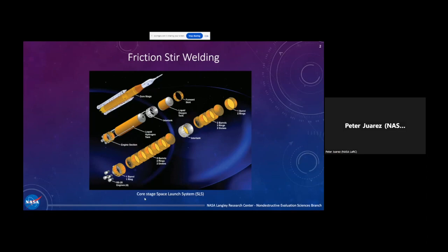The process of doing that is they basically take a spindle, plunge it in between the space of two adjoining panels, and then spin it really fast. The friction of that spinning and the mechanical actuation will sort of meld and mix the metals together very close to melting point, but not exactly melting. And the result is a very strong weld that retains the properties of the aluminum alloy and a complex grain structure on the inside. So anyway, we have this core section,